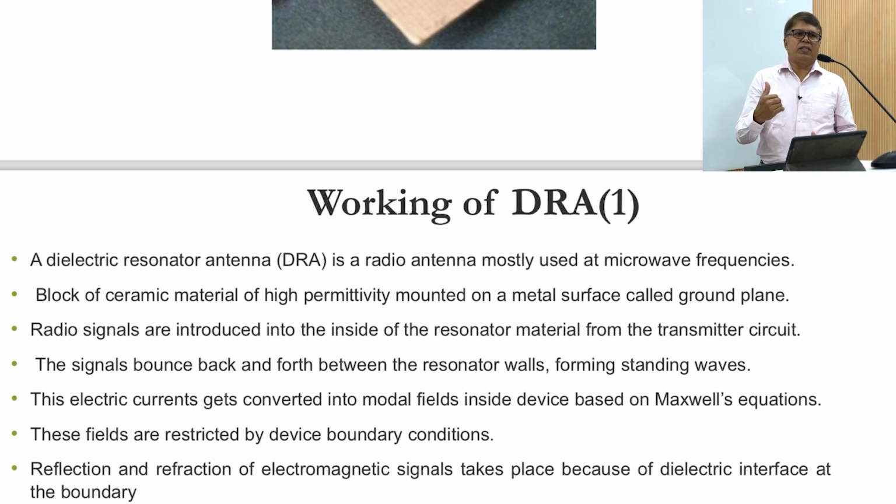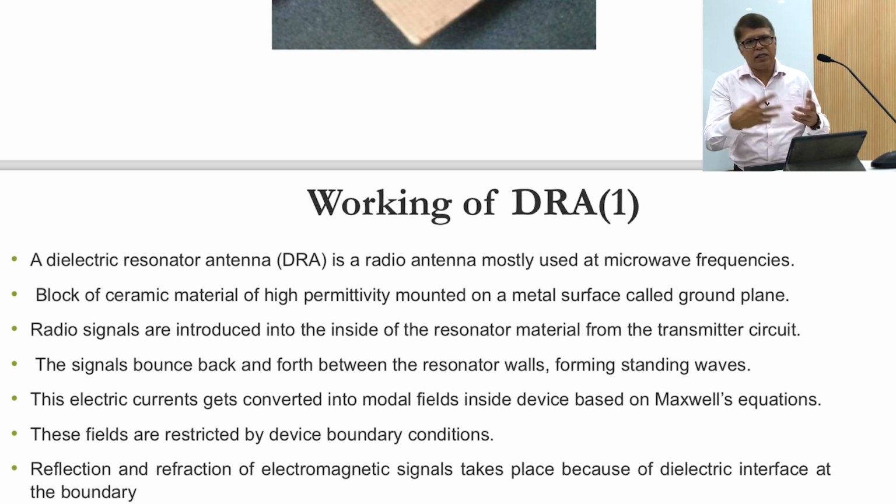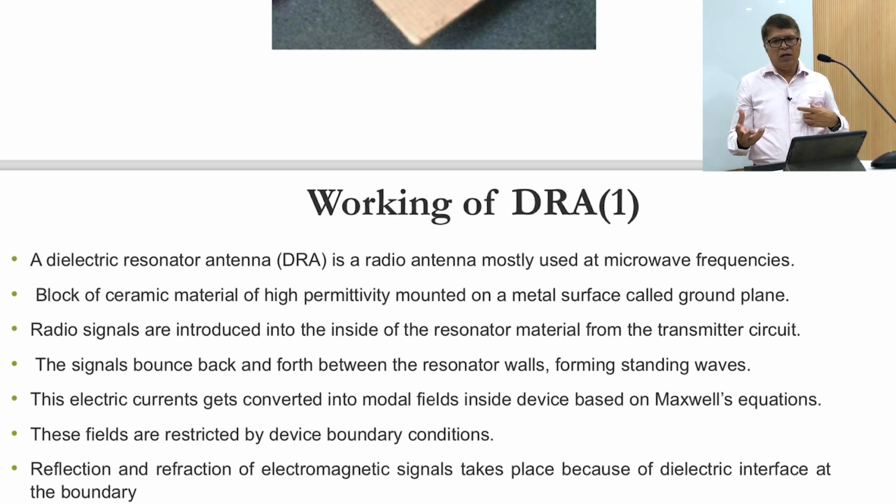In that, we target that we will be able to use the Schottky diode rectifier in combination with the CMOS rectifier, so that we are able to achieve lower voltages as well as higher voltages, and that combined effect will generate a huge amount of DC voltage, which can be used for IoT devices, or for the drone, where the drone battery life can be extended. So this is a use case where the flying time of a drone can be enhanced by using radio frequency energy harvesting.